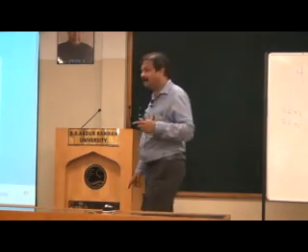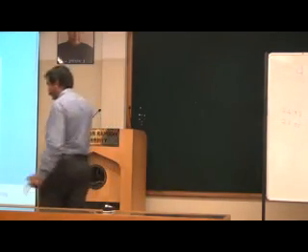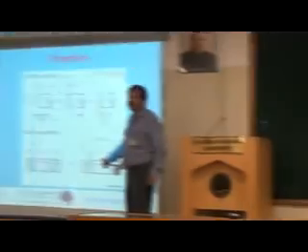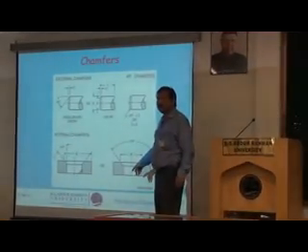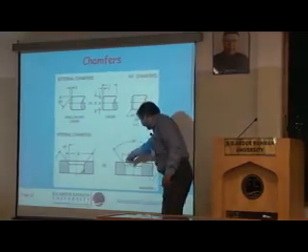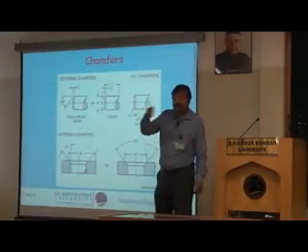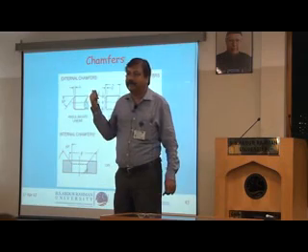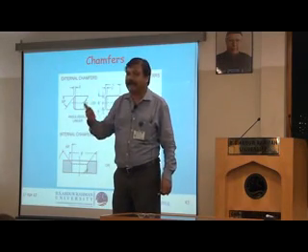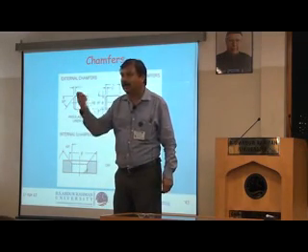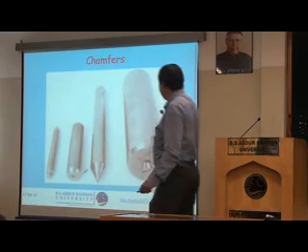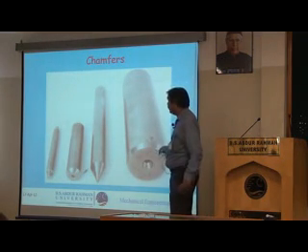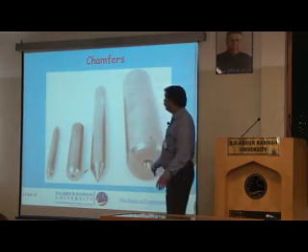If you don't have a chamfer on a bolt and a nut, and you try to assemble, it will be very, very difficult to put them together. So providing a small chamfer helps you a lot. And why I am telling you is, assembly practices are to be considered while you are designing. Next slide please. So you have a liberal chamfer here. This facilitates easy assembly.